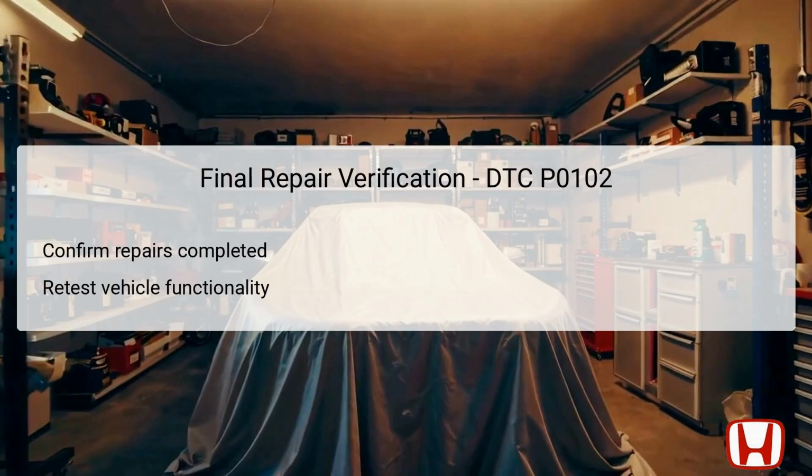Once all repairs and checks have been made regarding the MAF sensor and circuit related to DTC P0102, it is crucial to perform a final verification. This involves confirming that all repairs have been duly completed and verifying the efficiency of the fixes by retesting the vehicle's functionality. Utilize the HDS once more to ensure there are no remaining trouble codes present and to check that the MAF sensor operates within normal parameters. Each step should have been thoroughly validated before concluding that the issue has been resolved. Preventing future occurrences may involve maintaining electrical connections and keeping the MAF sensor clean. Ensuring these checks helps enhance long-term vehicle reliability.